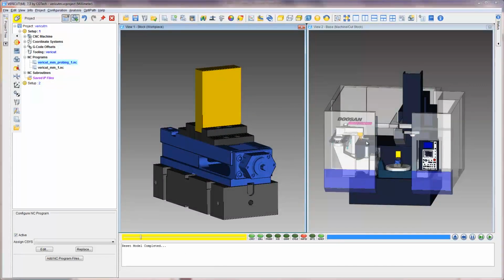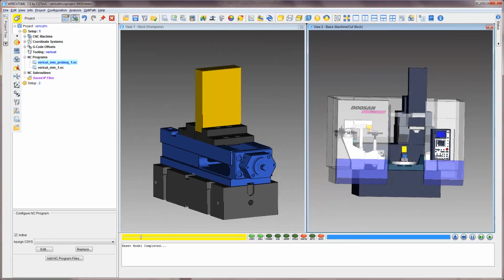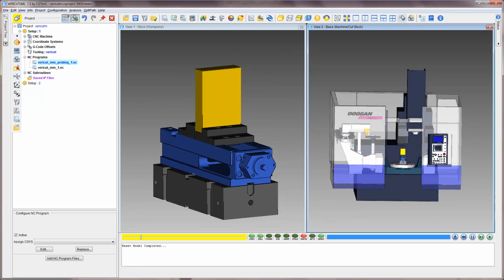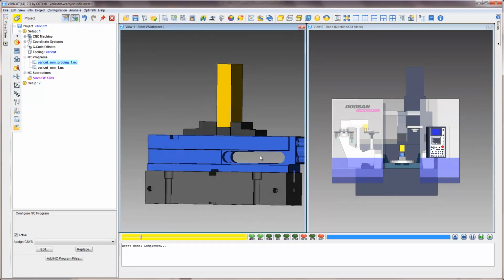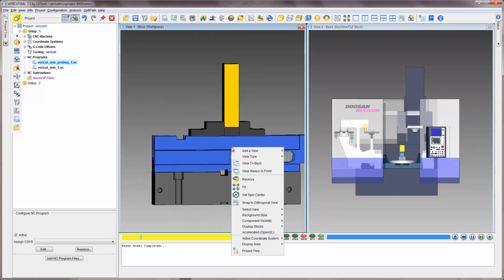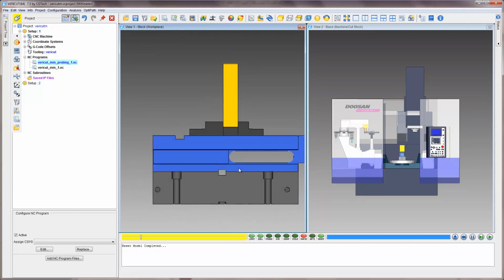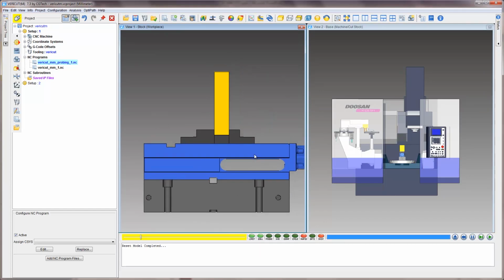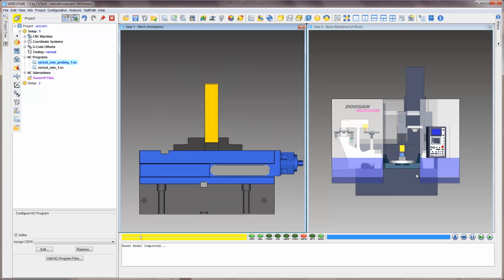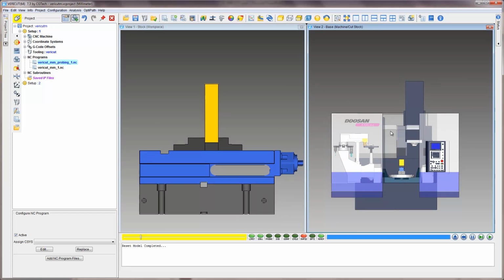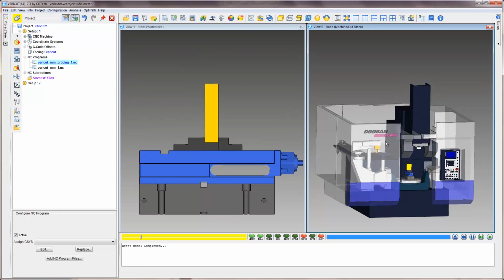First of all, let's take a look at the new snap orthogonal. This button here. So once you have something nearly lined up, just click snap orthogonal and it snaps to that view. So you can then pan and zoom, knowing that all your vertical lines will be vertical, horizontal lines will be horizontal. Just how engineers like things. We don't generally like things like that, do we?